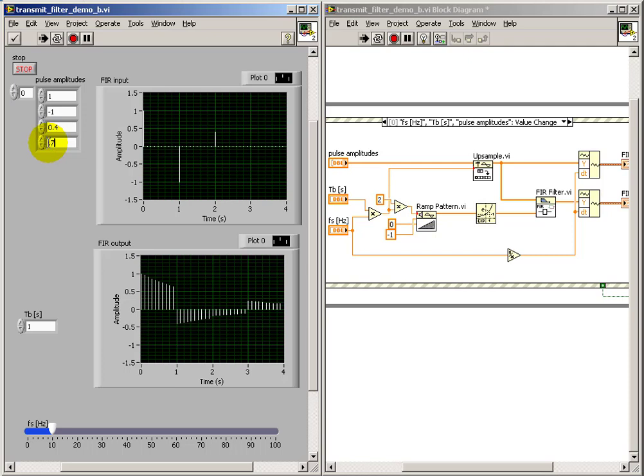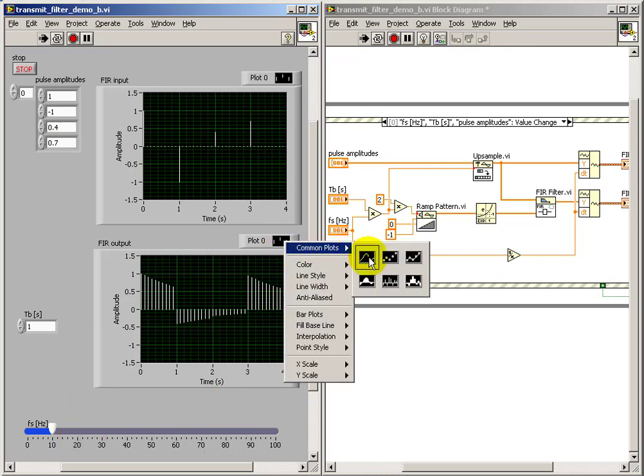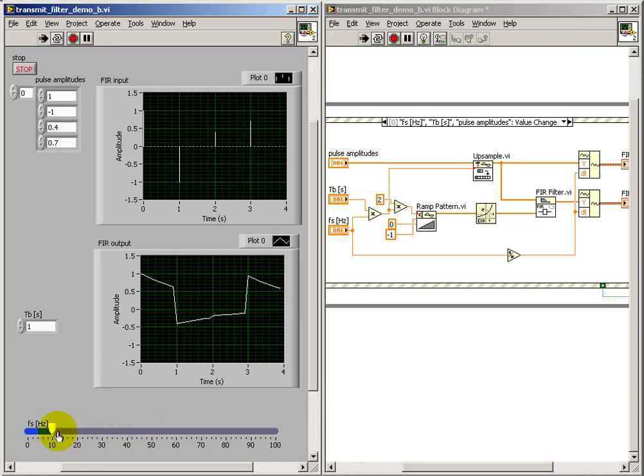So this works really well for us, and you can use really an arbitrary pulse shape once you've got this basic pattern set up. The signal point mapper will take care of generating the appropriate amplitudes on the upsample device, and then the FIR filter will apply whatever your desired pulse shape is to generate the signal before it gets to the multiplier for modulation.